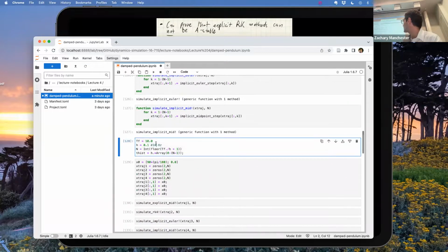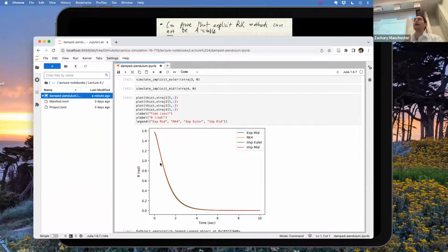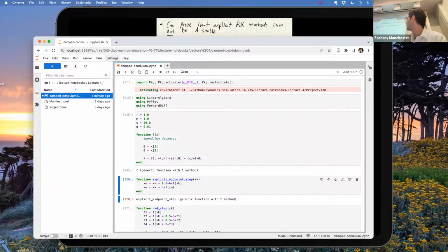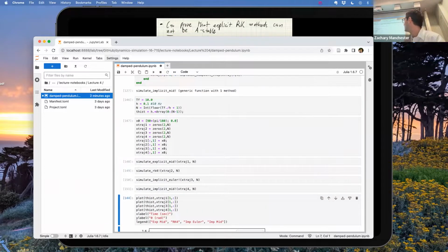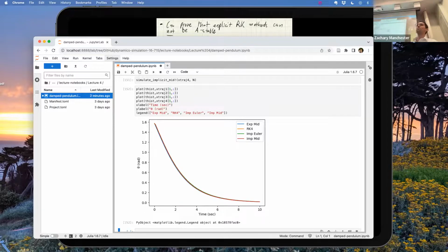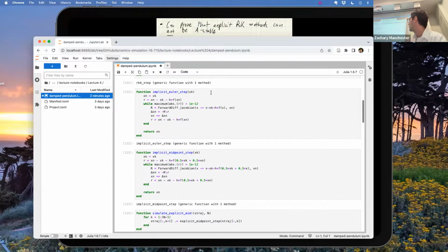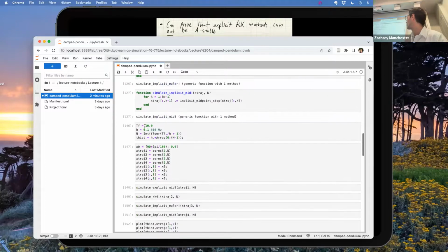This is getting at the whole point: these all do okay. Now it's overdamped, so it's just going to fall down. If I keep jacking this up, what you'll find is eventually, again, there's nothing in terms of sample rate here. There's nothing happening faster than 10 hertz. In terms of Nyquist or whatever, it's all super slow, so 10 hertz should be plenty from that perspective. Let's see. I think this is where it actually breaks now.